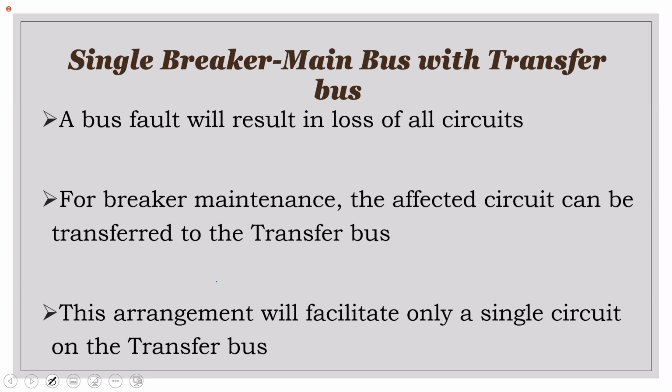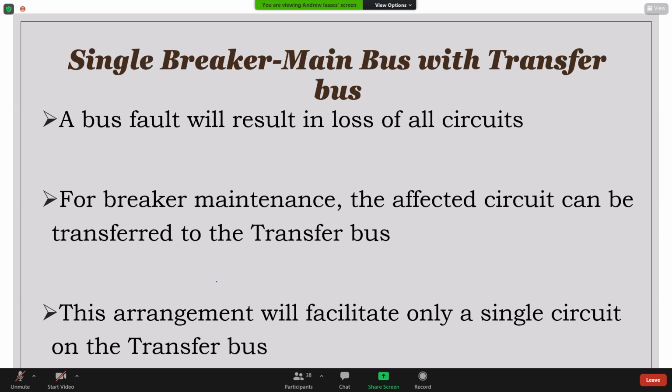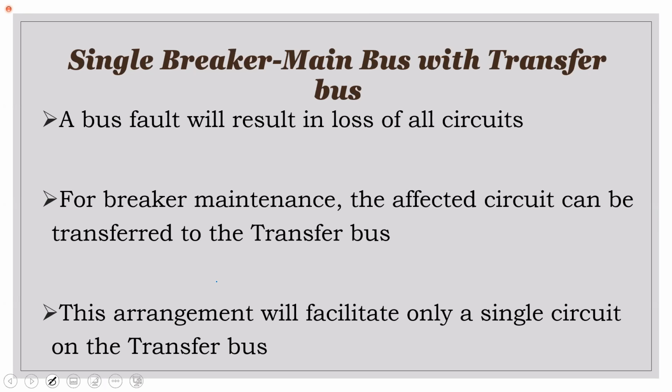And if we go back to what I said earlier, in terms of considerations, the bus arrangement is used to facilitate 1, the number of circuits, 2, maintenance, and 3, we consider the fault implications. And then what we use will be based on the service requirements and, of course, cost. So far, in terms of cost, the single breaker with double bus with bus tie may cost a little more than the single breaker single bus because I have the tie bus breaker included.